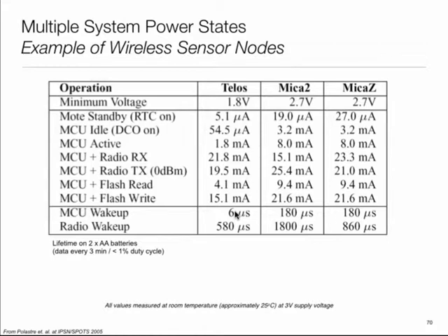What is happening in that 6 microseconds? You know what I'm saying, right? This is interrupt to the first instruction, so all these other issues that we were talking about are not there. And in this particular device, the memory contents are preserved, so we don't need to restore it. So what all do you think might be responsible for this kind of a number?